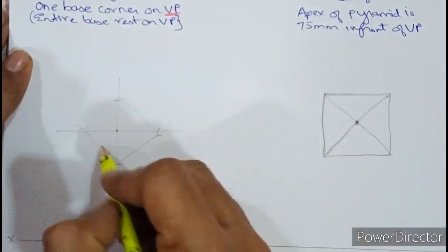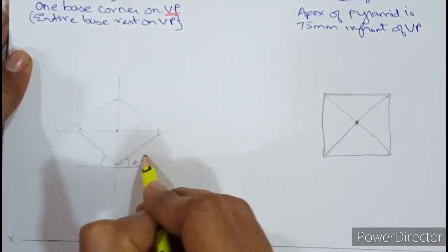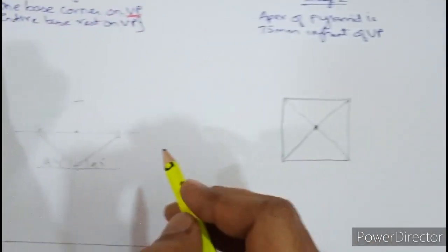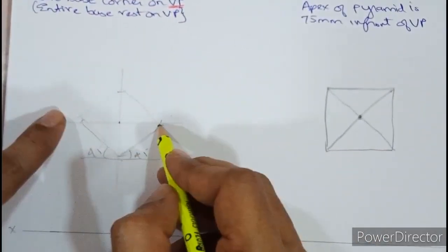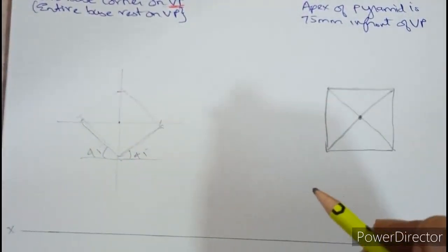The second option to draw the square is, both the sides are inclined at 45 degrees. If you don't want to spend time drawing the square outside, you draw two lines at 45 degrees and mark 50 on them and then continue with drawing the square. We'll follow method number 2.